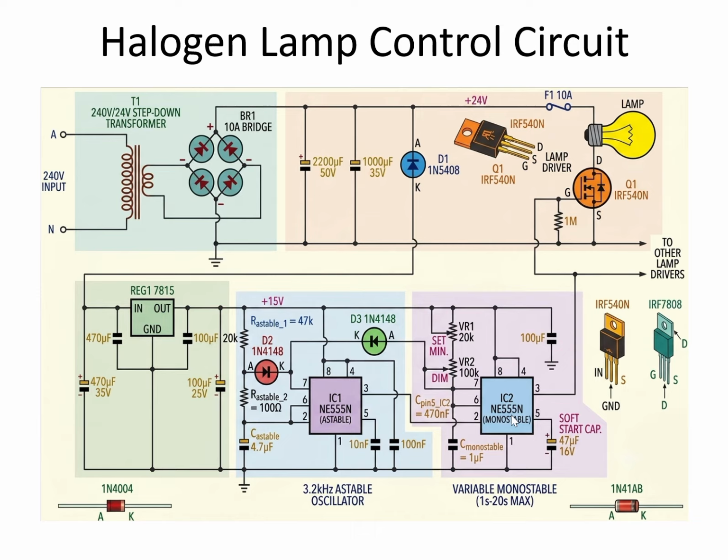The frequency may be varied by adjusting the resistance and capacitance values of the 555 IC timer. The resistors, capacitor and diodes determine the charging time, discharging time, and the frequency of the square wave pulses produced by this oscillatory circuit.